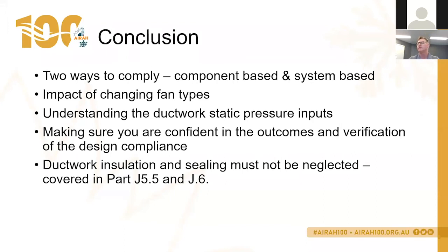So yes, you still have to do all of the efficiency calculations or determine your system minimum efficiencies, because that's the data that goes into your reference model, so that when you do your proposed model with your actual fan, you have something to compare against.